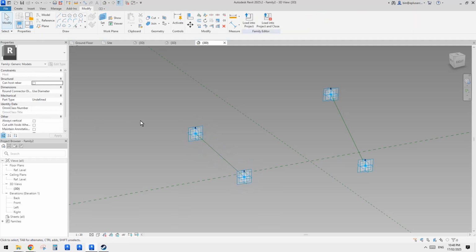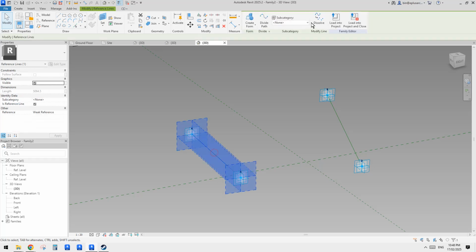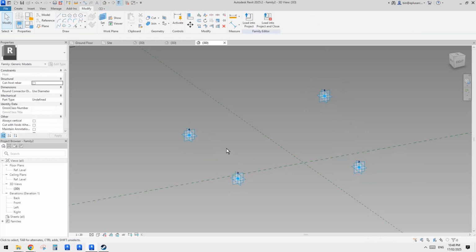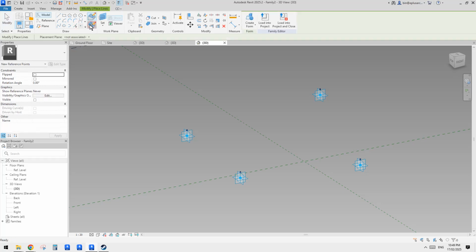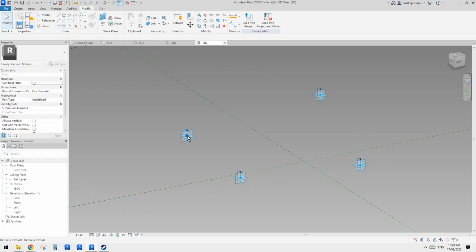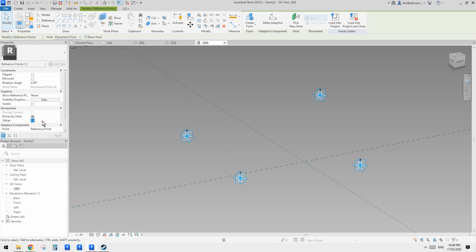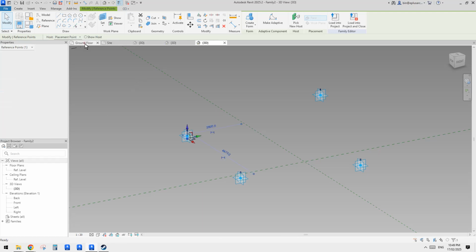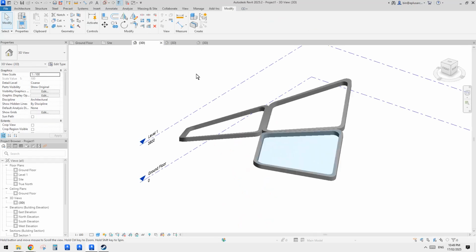Instead of directly creating splines through all these points, I'll just place a point, use draw on work plane, set work plane, pick the horizontal work plane, place this point, select this point, and go down. So I can just imagine the thickness of the roof. Whatever that roof is, I'll just have a look. Okay, so it might be 400.